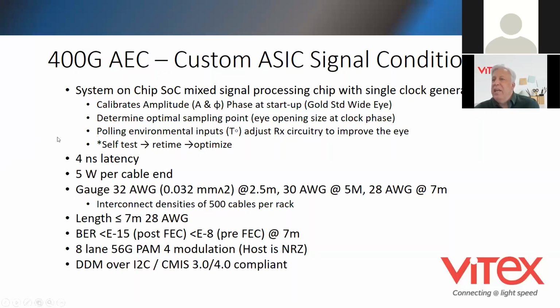The latency on the AEC is actually pretty good. It's 4 nanoseconds at 400G. The power consumption is 5 watts per cable end, so 10 watts for a cable.